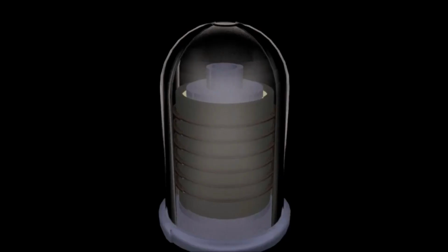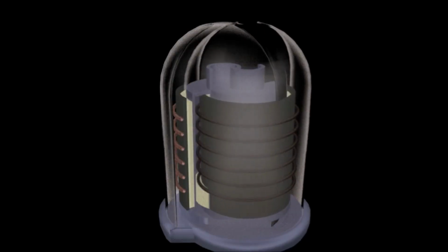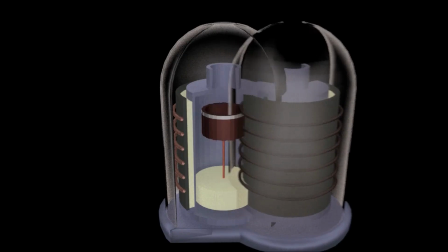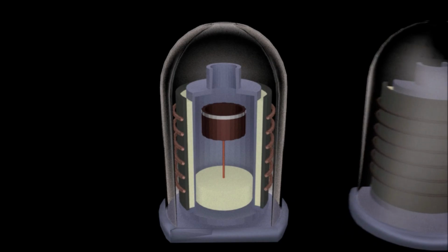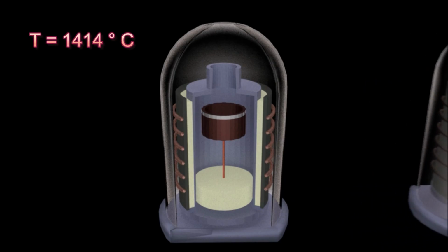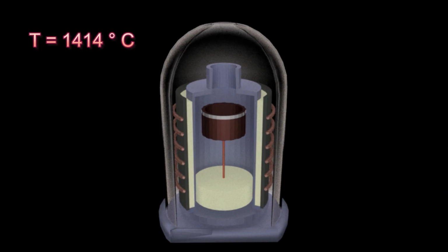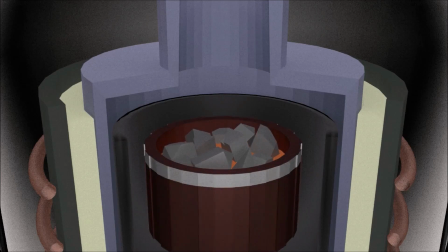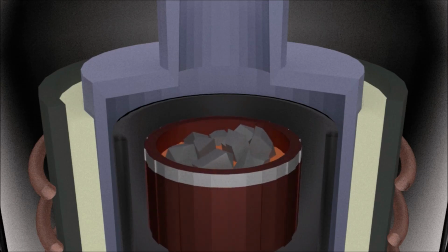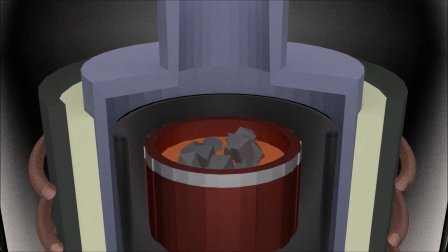In order to create monocrystalline silicon, the ultra-pure polysilicon produced during the Siemens purification process is melted once again inside a quartz crucible. This occurs at temperatures around 1414 degrees Celsius, which is the melting temperature of silicon. Inside the furnace, the silicon becomes fully molten. The temperature is controlled with extreme precision and the environment is carefully isolated to avoid contamination. And this is where one of the most remarkable processes in modern materials engineering truly begins.